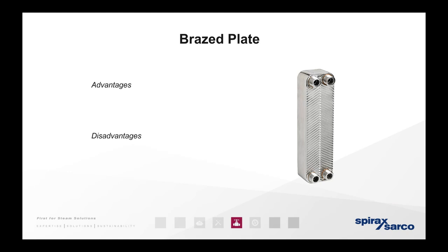And for me, I've done a lot of work on CIP heat exchangers, and gasket free, like a Turboflow, is the best option. Whenever you've got a caustic or acid, I would try and steer away from gasketed plate type heat exchangers. Yeah, exactly that. It's always CIP or secondary. So steam is neutral. It doesn't really cause any damage to gaskets. Obviously there's heat, but it's the media you're trying to heat and the CIP you use to clean it that cause the issues. So it's just the normal chemical compatibility charts on that.